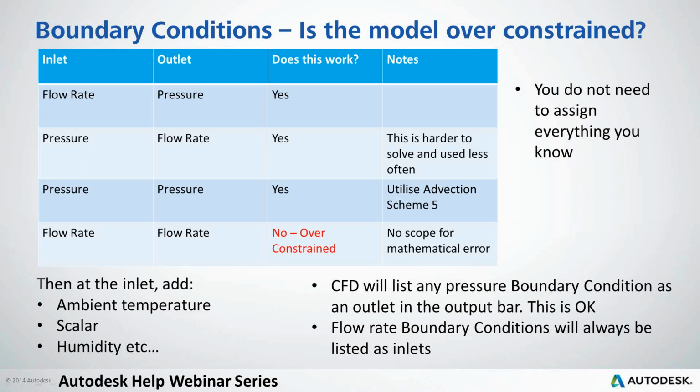Just to talk first about engineering checks, you've got to do them after you've run a model. Make sure that you've got mass balance, energy balance. There are simple checks that you should run on every model.